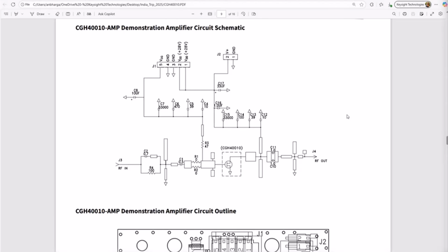Many times I have seen people start their design with very idealistic things, everything is nicely connected. And then once they reach the layout stage and they start doing EM simulation, EM circuit co-simulation, a lot of those things vary drastically. I've seen gain dropped from 15 dB to 5 dB. And then people scratch their head trying to figure out what happened. Well, that's what happened. And I have a practical paper on that.